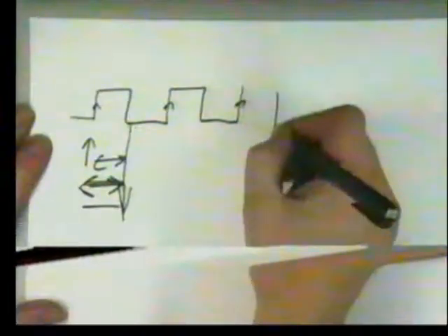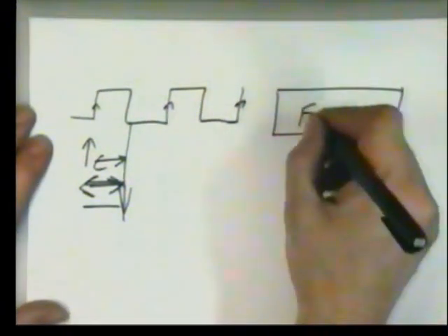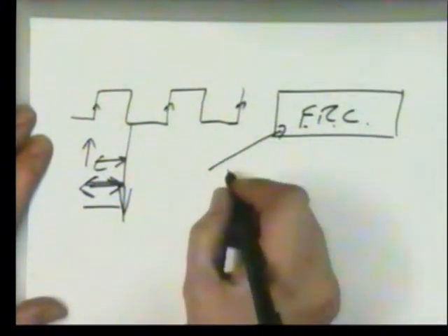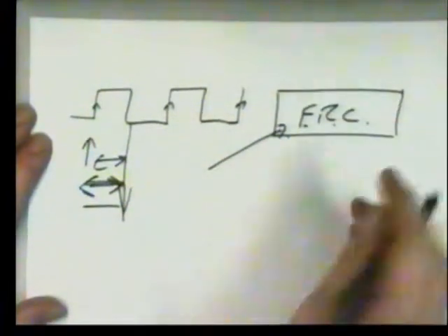The other way to do it, which might be a little bit better, let's not forget, we have here the free running counter. That is memory mapped, so we can view that at any time to see what the time of day is. So now we can use a polling technique. If we know that at such a time of day we have to take our signal low, every now and again we keep looking at the free running counter. When we see it reaches that time, and remember, use a greater than or equal to, because you want to be equal to or past it, then you take the signal low, so you can poll.